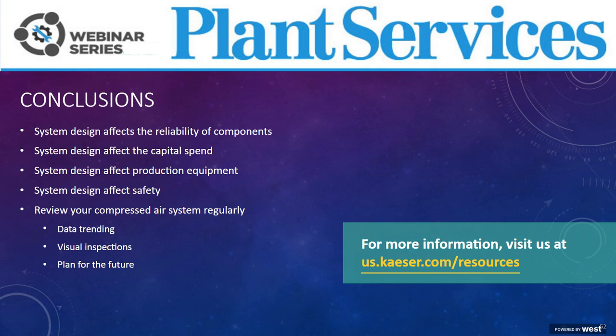Locate the compressor station near that opportunity. If it's a food plant, you always do clean in place. You're using hot water. Use water cooled machines. A 100 horsepower compressor is basically a 75 kilowatt heater. You might as well use that heat. It's a BTU to BTU offset for whatever you're using to heat the water. But that would be the first thing.